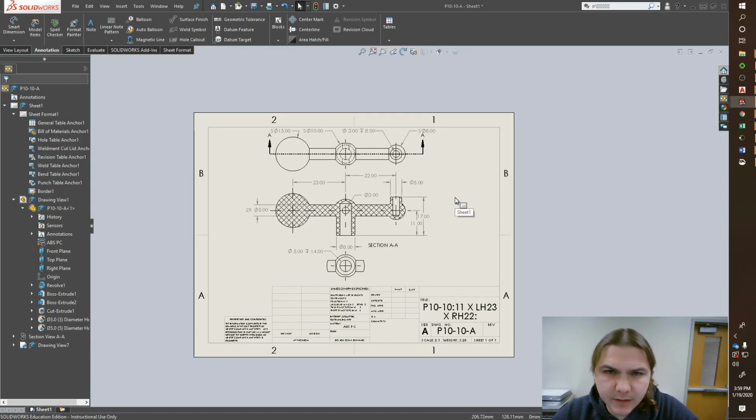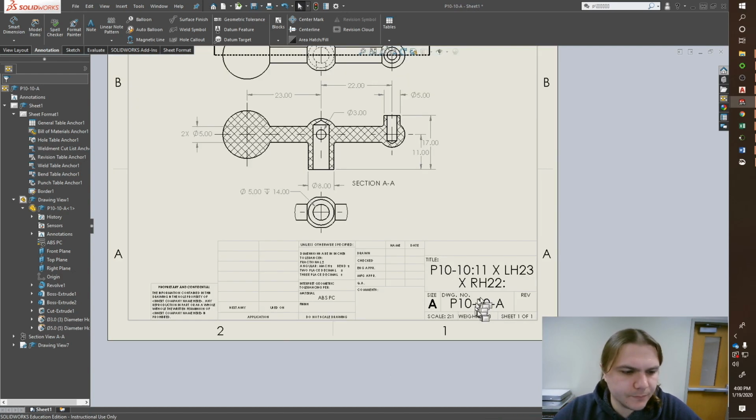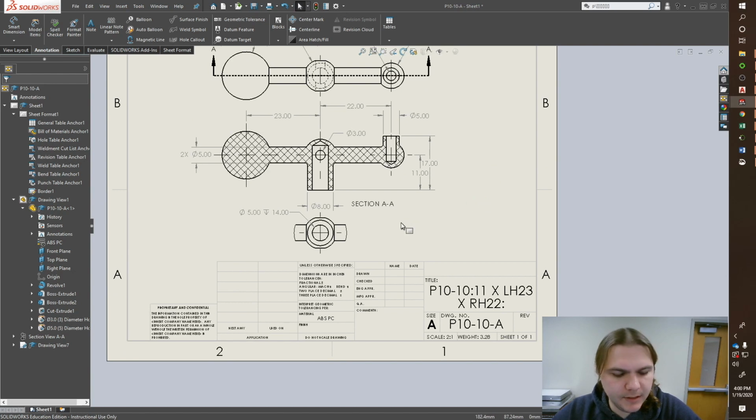If you see any dimensions in your drawing that turn yellow, that means they lost their association to whatever you had initially dimensioned them to. As far as I've tried, regretfully, it seems like the best path to fix it is just to start over. I played around with it a little bit, but so far it's just been more of a pain in the butt than just doing it from scratch again. Everything got updated. I'm going to hit save.